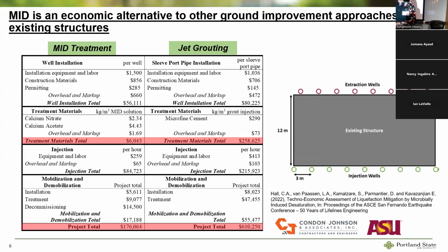It is a little curious, because I would have thought once we desaturated a fine-grained soil like this, it would persist for a long time due to surface tension and holding the bubbles in the pores. It should persist longer than sand, but this suggests that it's faster than some of the cases we looked at for sand. It's curious. That's why it's research.